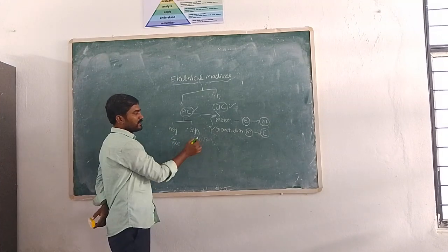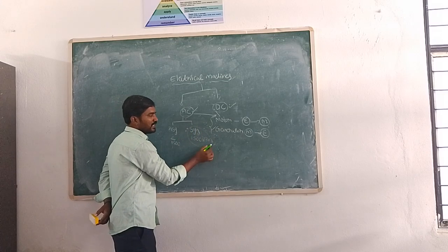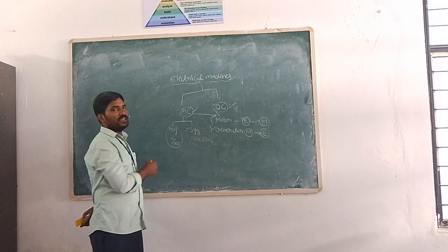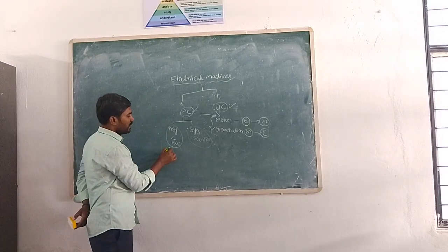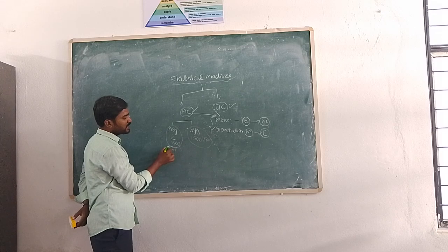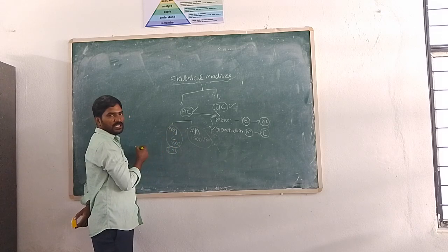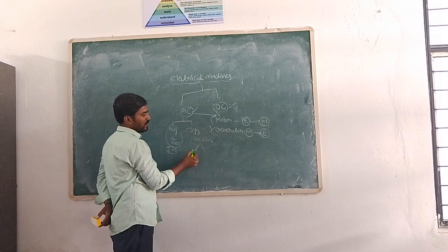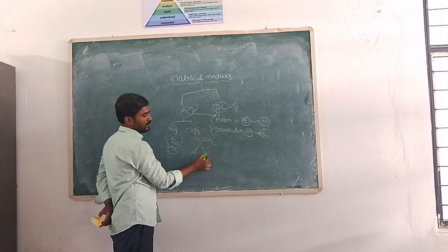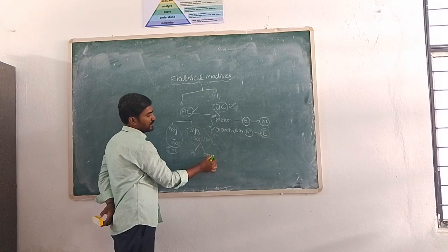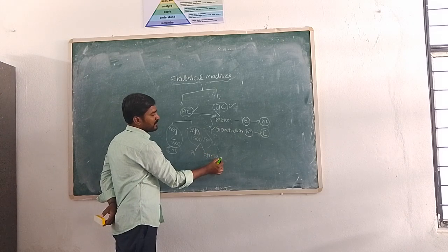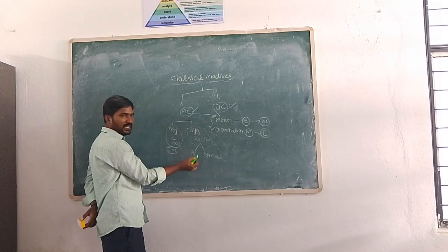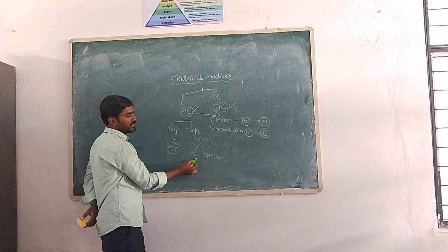In the case of synchronous machines, mostly those are doubly excited machines. But in the case of asynchronous machines, mostly those are singly excited machines. For example, induction motors are called asynchronous motors. Synchronous machines are further classified into two categories: one is alternators and the second is synchronous motors. These are the basic classifications of synchronous machines. For example, if it is producing alternating current, acting as a generator, simply those are called alternators.